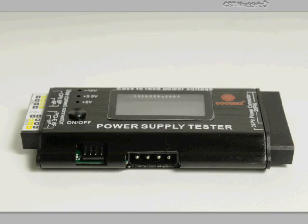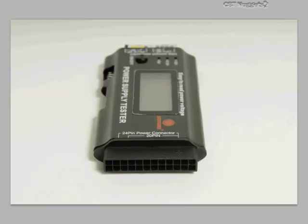If I go to this one right here, this is one I think I showed you early on in our series. What you see is that you can plug a number of different kinds of connections into this, like a Molex connector here, for the kind of connection I would put onto my hard drives, like IDE drives or optical drives, for example. Then we would have here a Berg connector for my floppy drives. If I flip this around, I think I have some other images of this, then we can plug in our 24 or 20 pin power connector that goes to the motherboard. So that's just another connection that we can make there.